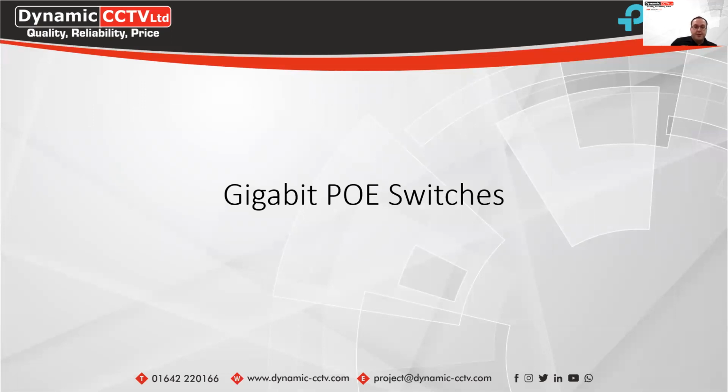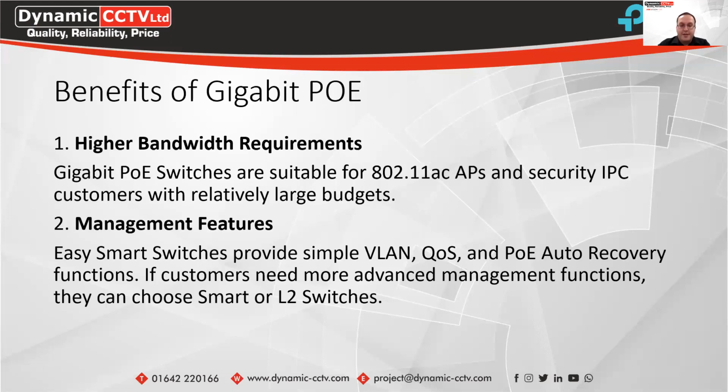So now we can move on to the gigabit PoE switches. These obviously have the high throughput, and it's a gigabit port per connection on the actual switch. It's not just the uplink ports on these ones. So the main benefit of gigabit PoE is obviously the high bandwidth.